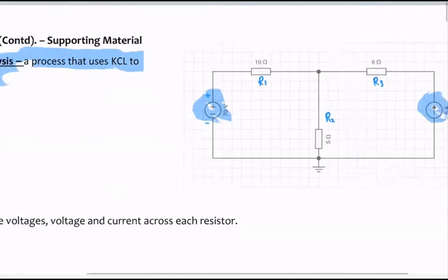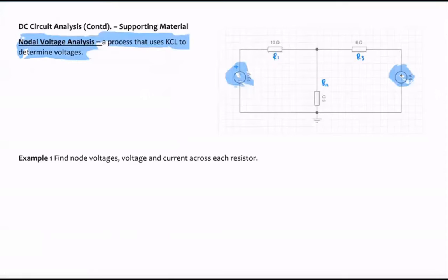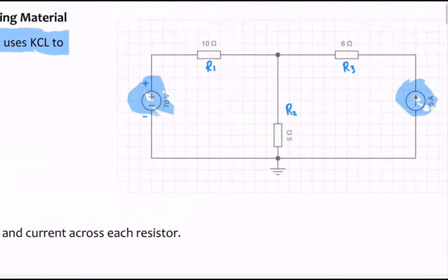When you are doing nodal voltage analysis, there are a few steps that you need to take, and then it becomes a lot easier to do the analysis. Also, before I get onto those steps, since we know the polarity, we can draw the direction of the current flowing into each of these components. So you have this current flowing over here in this direction, right? And then we'll go here. You also have this current source coming from here, going past this R3, and then these two currents right here will merge at this node, and then this will go right here.